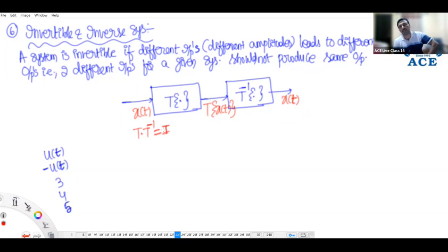Where we require this invertibility concept is in entire communication, signal transmission. Once we apply some form of input, because of the internal components, it may get distorted. To cancel the distortion, we use an inverse block called an equalizer.